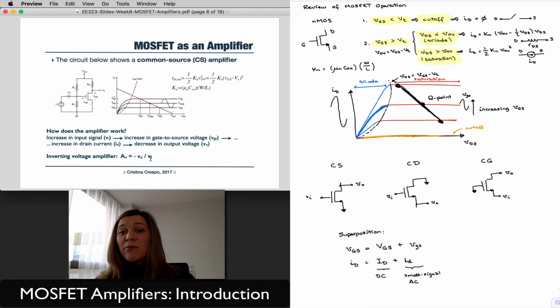All these different voltage amplifiers are going to have some gain factor. The gain is going to give me the relationship between the input signal and the output signal, which is great. And then the only other piece of information that I need is how these amplifiers are going to interact with each other when I connect them together. And that's given by the input-output characteristics, or the input resistance and output resistance.